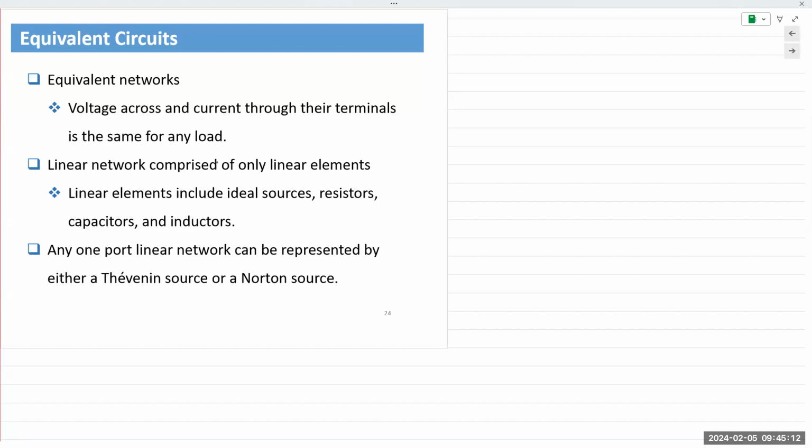In a resistor, if you increase the voltage, the current increases in direct proportion, okay? And hence it's linear. The relationship between voltage and current is linear. So Thevenin and Norton apply to linear circuits only. This is not something you have to worry about, because the only analysis we perform for Thevenin and Norton is on resistive networks or resistive circuits. So it's all linear circuits.